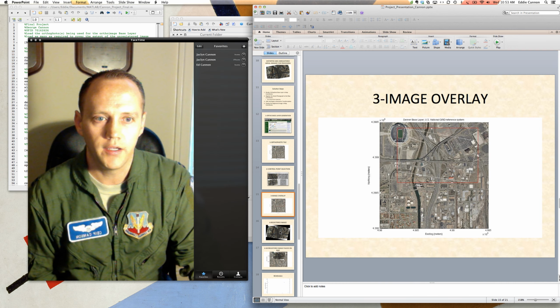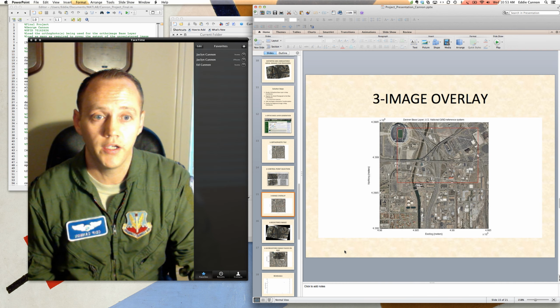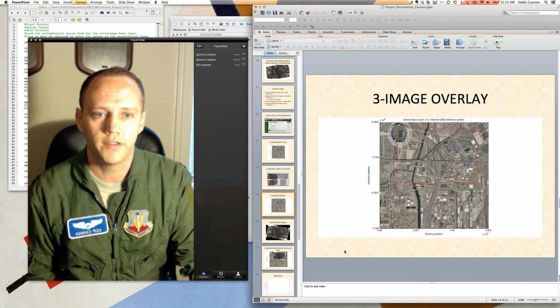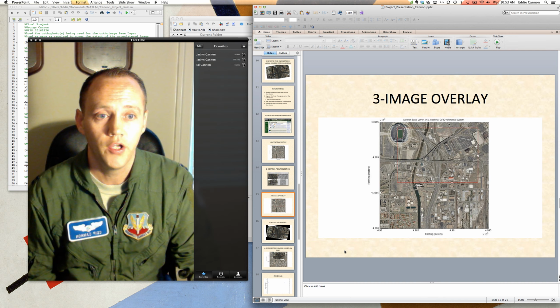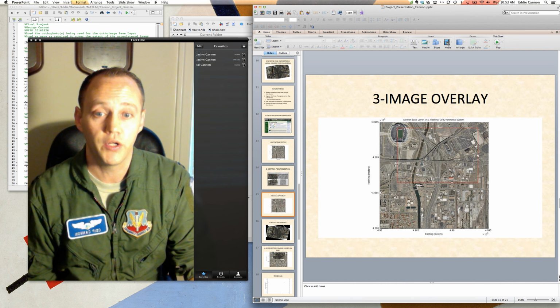In our case, we ended up georectifying to a 1 meter resolution based on the image quality. So within that red bounding box, we're no longer talking 0.6 meter resolution with the image. Where the image is placed is now going to be down to the meter resolution for each pixel.